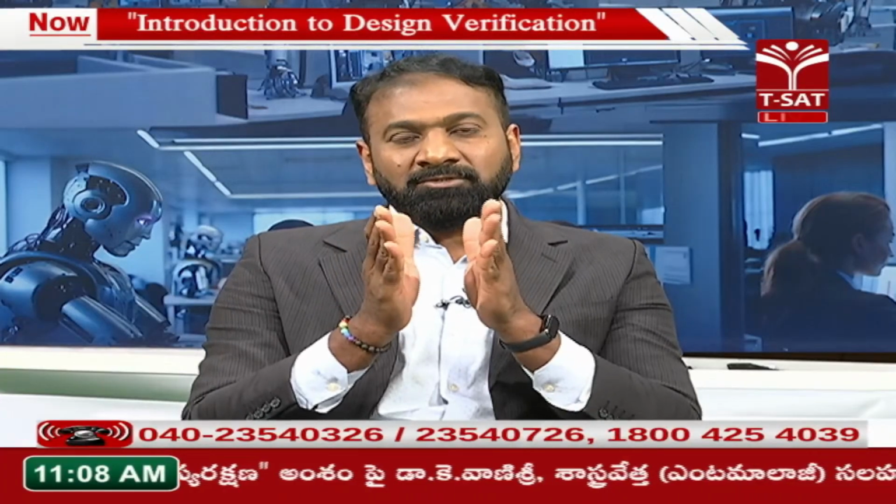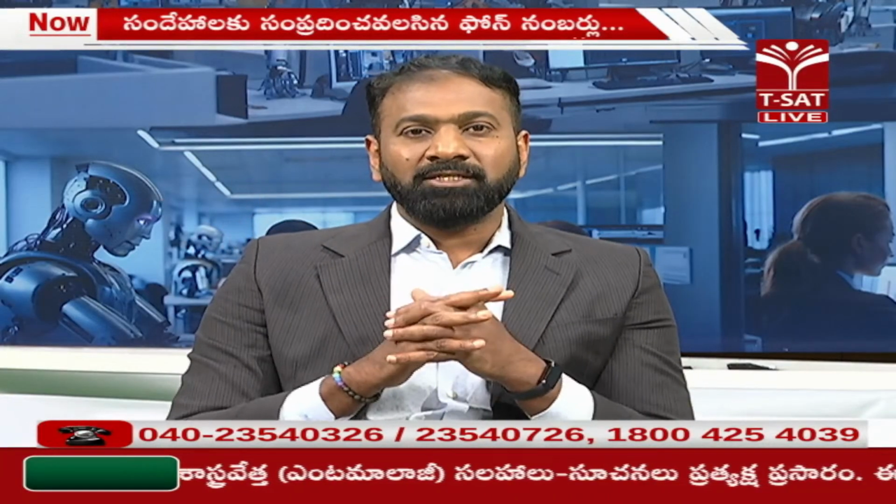You may not, right, unless you have some delays. So when you are traversing from one clock frequency to another clock frequency, there is a possibility of data loss or synchronization issues. If you want to catch such kind of clock domain crossings, you can use static verification, which can help you to identify such kind of clock domain crossings.